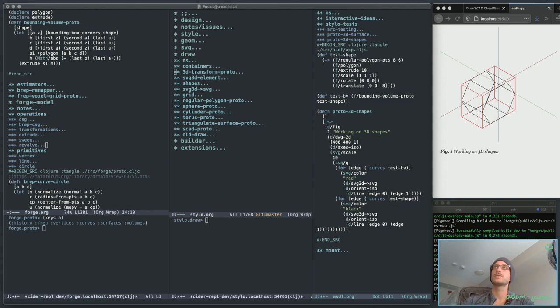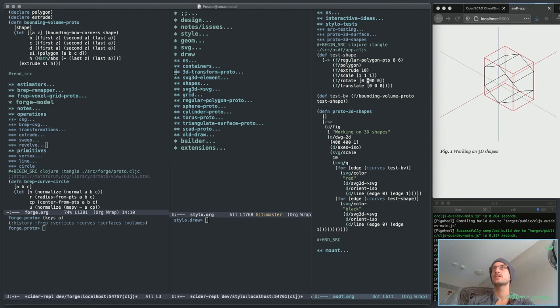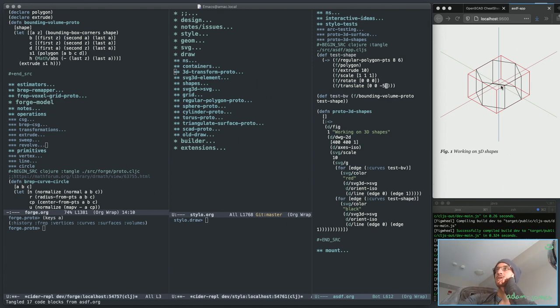But let's go back to what I had here. Let's even do -90. And then finally here, translate should work no problem. So if I actually rotate it 0, extrude is 10, if I translate -5, this should be the center of this volume, just coincidentally going to be exactly at the center of the axes here. It didn't do that automatically, it's just the logic of how I am calling this shape, that's all.